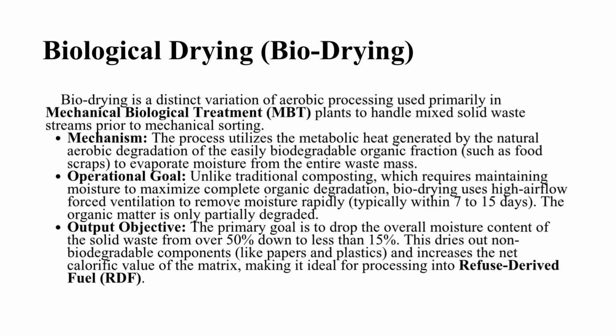Typically, moisture content is reduced from more than 50% to below 15% within 7 to 15 days. This significantly increases the calorific value of the waste material. The dried waste can then be converted into refuse-derived fuel, or RDF, for energy generation. Therefore, biodrying serves as an important pre-treatment step in waste-to-energy systems.